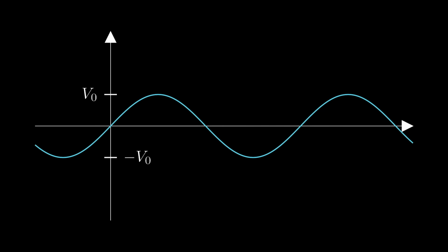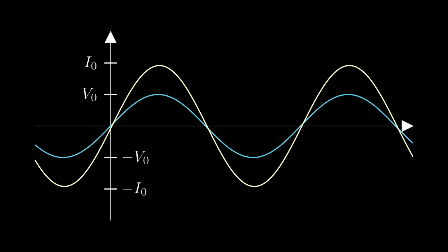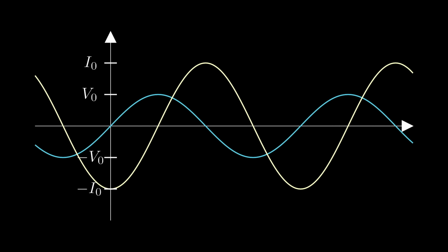Looking at the sine waves, it's going to lag behind the other voltages in the circuit, since it opposes changes in voltage. So we can shift it to the right because, remember, further to the right means further into the future. Now if we start looking at this peak right here, we can see that the voltage is at its maximum. At this point, enough voltage has been applied to get the current running through the inductor, and it'll keep running more and more as we push it more until we start pushing it in the other direction. And then the voltage in the inductor will start to slow down more and more again until we're at the peak voltage on the other side.